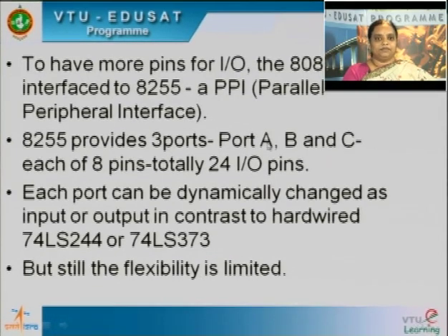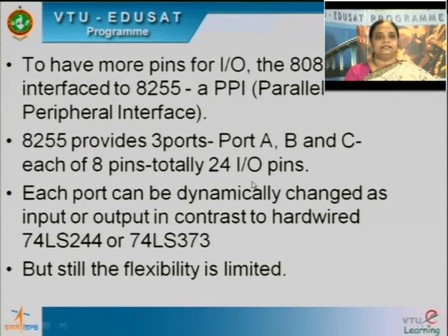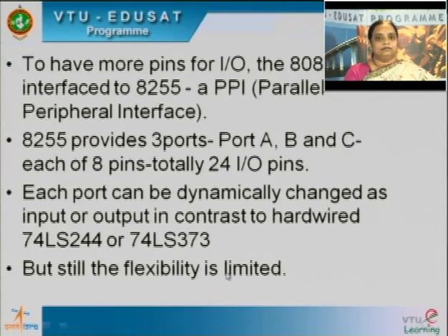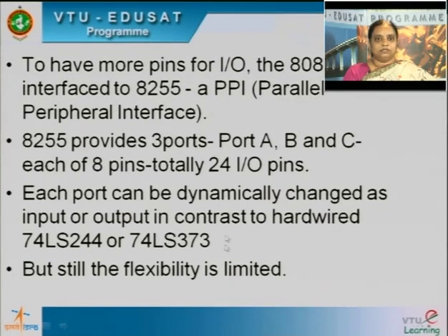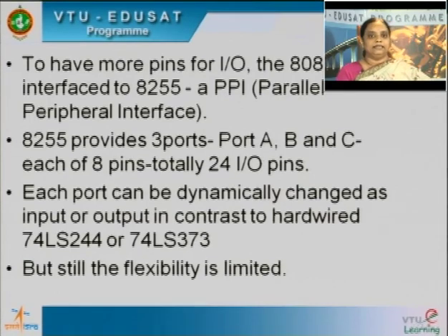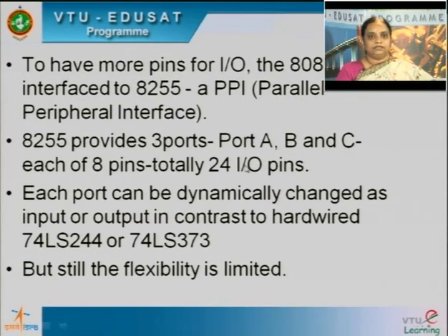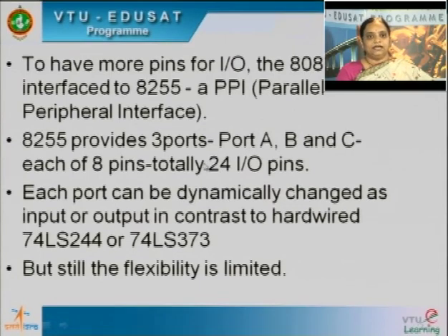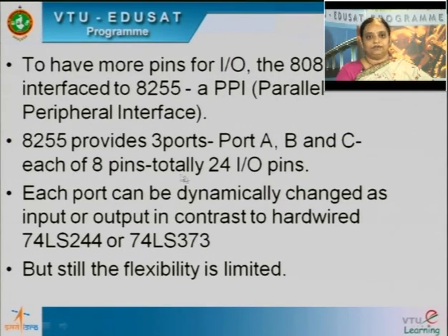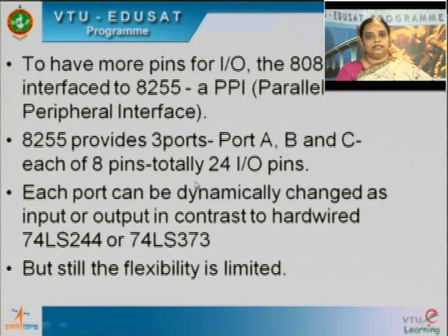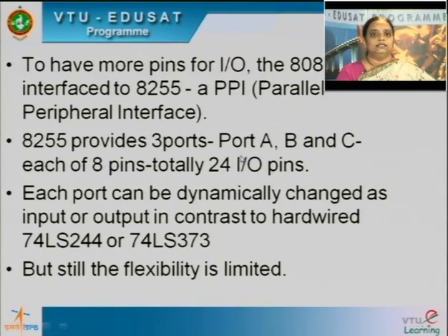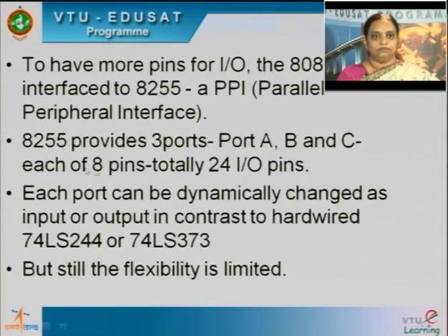If I configure port A as input, the whole 8 pins are configured as inputs. But in the latest microprocessors and microcontrollers, each pin of the port can be configured separately as input or output. But that's a different issue. So here we are in 8255. In the 8255 there are 24 I/O pins, and in these 24 I/O pins you have 3 ports.